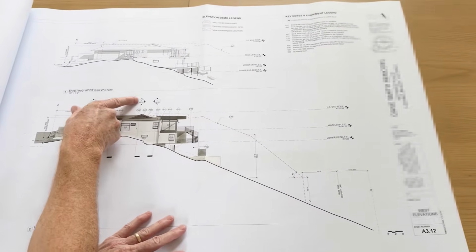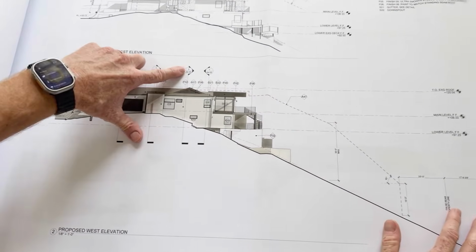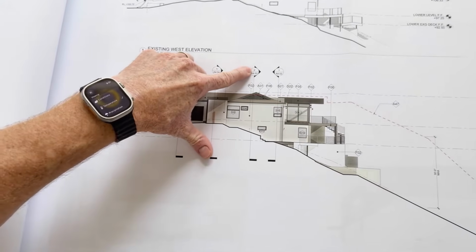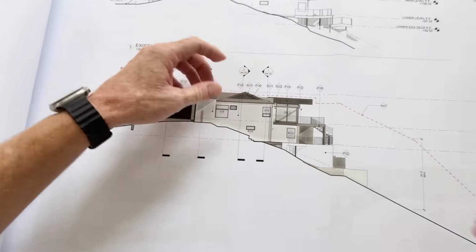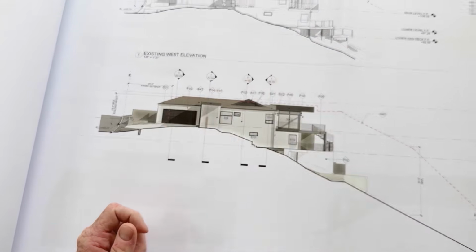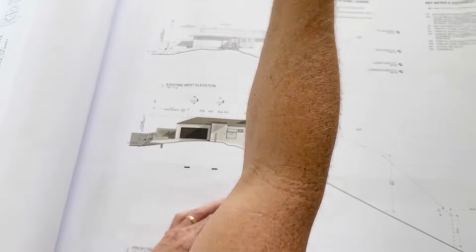Follow it this way. These are our cross sections. Okay, so with the elevations comes, just like we had on the floor plans, we had lines running through the building. If we follow and take a look at this 2 on A4.03, this line right here, we open up that section, it's going to show us what is inside directly, this line from this side of the building all the way to the other.